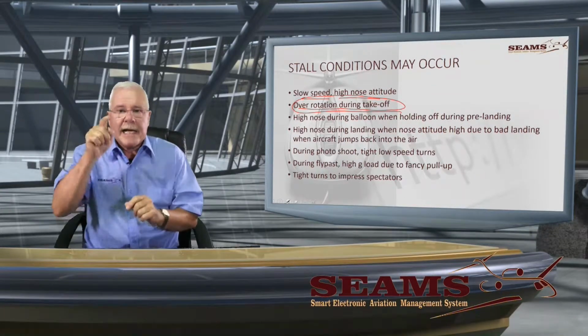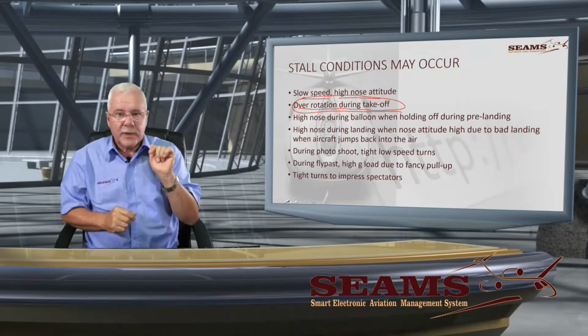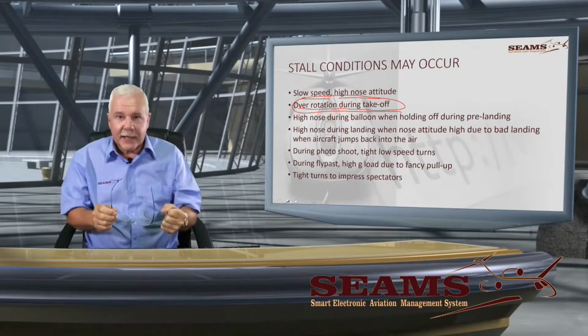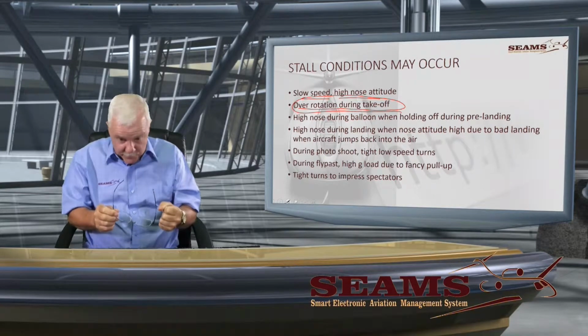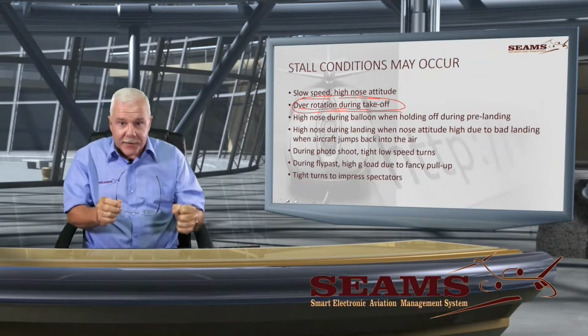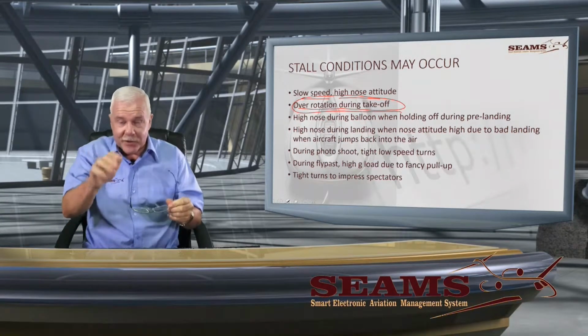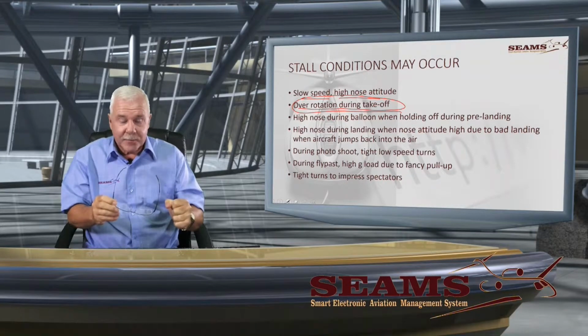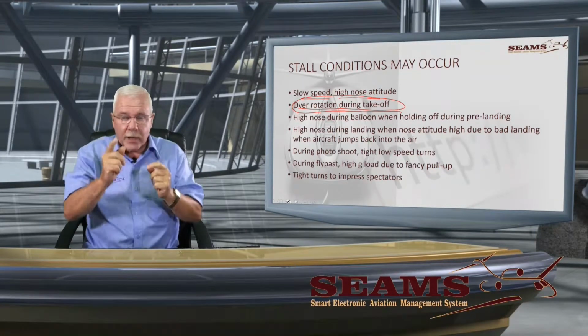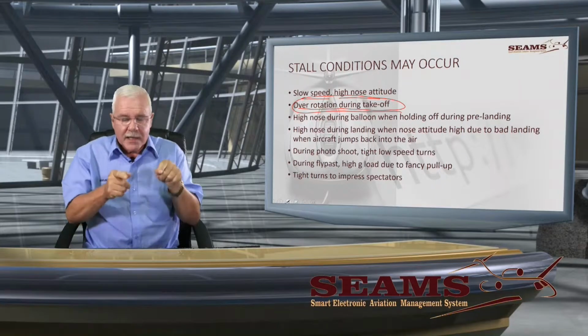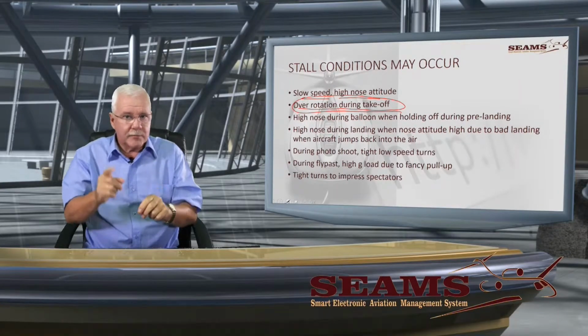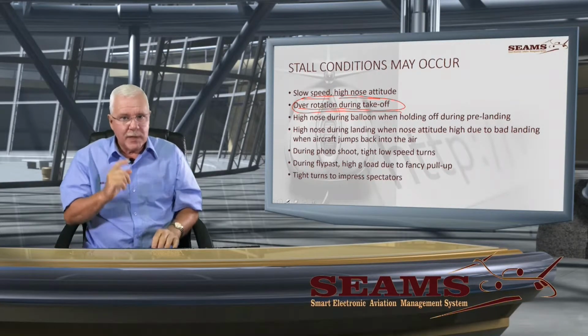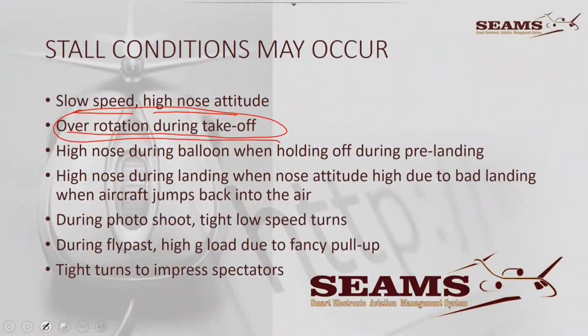Where do you look? Outside. And you peep inside. Look at my eyes. I'm flying outside and I peep inside. I don't do this with my head. I'm flying outside, I see the attitude, I change the attitude, I look at the speed. I see the speed is a little bit low. I look outside, I change the attitude, I reduce it slightly. There it's right, and then I peep inside. So you look outside and you peep inside. Inside, if it takes all your attention, you're going to be in trouble. And many people have been in trouble.